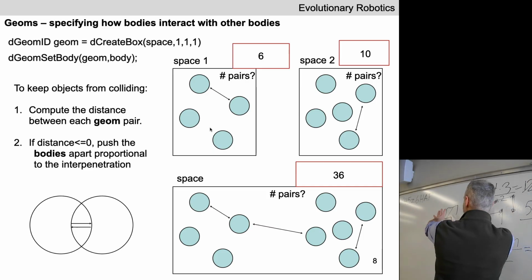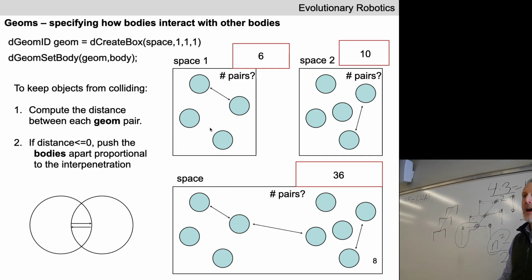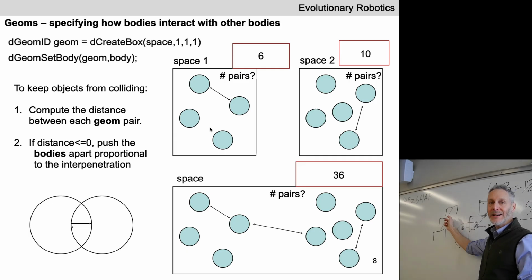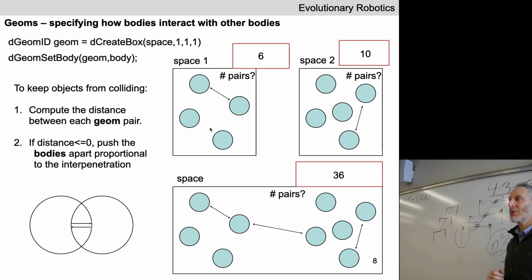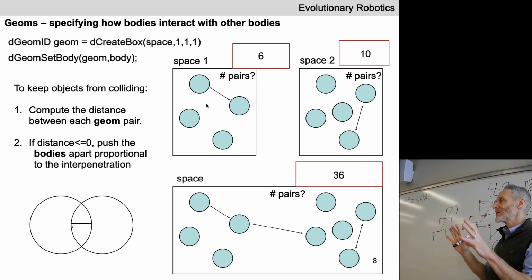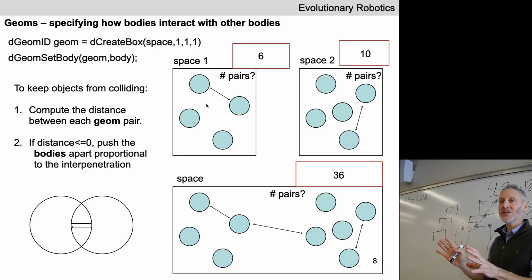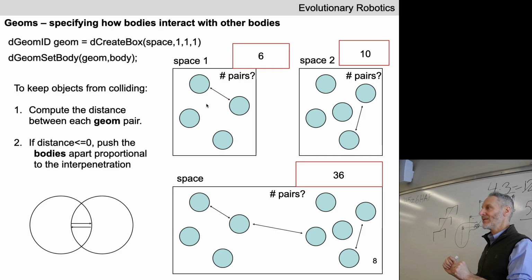What happens when the 2 collision spaces surrounding the 2 robots come into contact with one another? What does the physics engine have to do during that time step? It has to now check collision between both of the robots, between every link in every robot against every other one. So hopefully you can see the intuition here. Collision spaces restrict the amount of computational effort that your physics engine has to do most of the time.